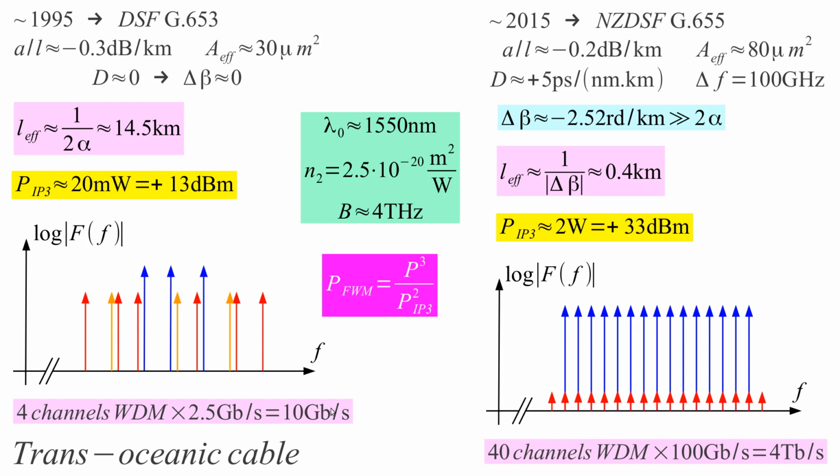In fact, these cables could only do 4 channels WDM at 2.4 gigabits per second to span the ocean just with 10 gigabits per second. This was the technology 30 years ago because of this inadequate fiber. And if you calculate the power here, all links are considered always at 1550 nanometers, always with the same kind of glass and with the same bandwidth.